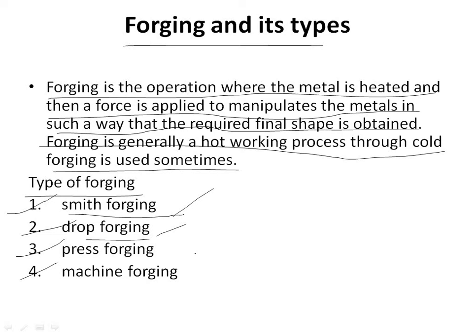The heated stock is kept in the lower die while the ram delivers 4 to 5 blows on the metal. The metal spreads and completely fills the die cavity. When the two halves of the die are closed, the component is formed.